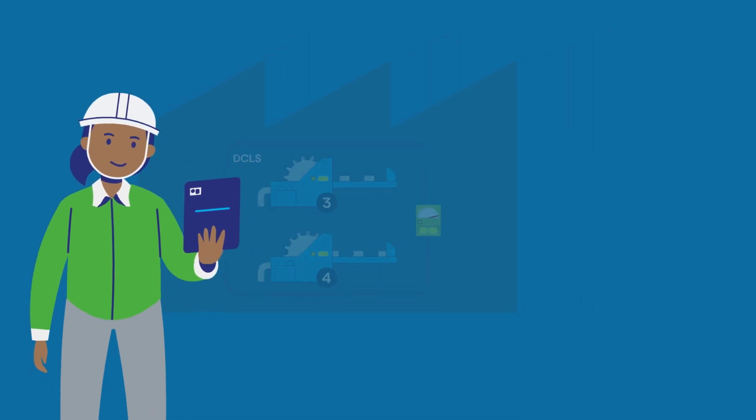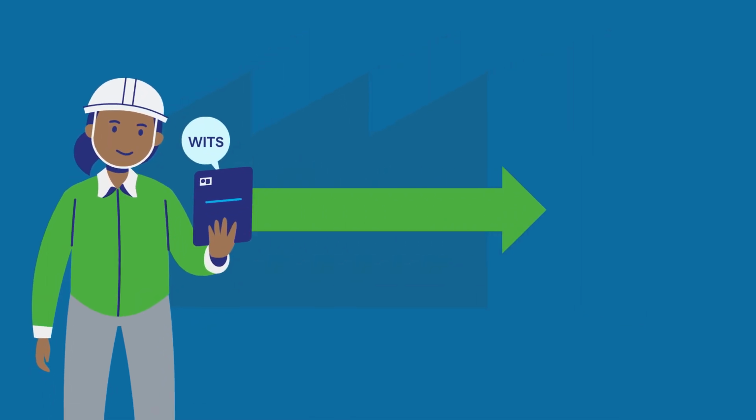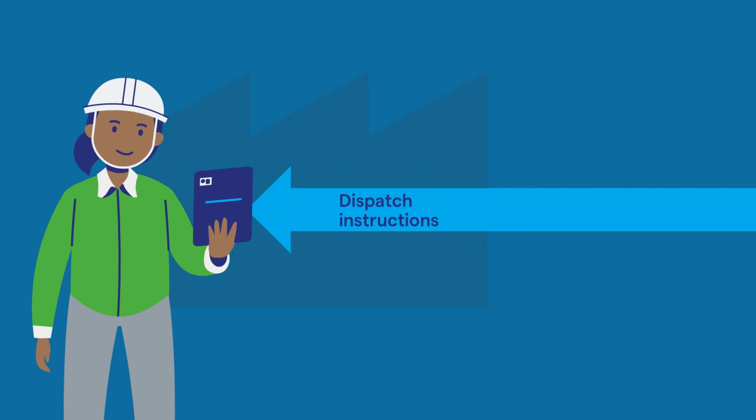Now, as part of the usual running of her factory, Sarah will enter dispatchable bids for each trading period. The bids indicate the megawatt amount of load Sarah needs to run the machines and the maximum price Sarah is willing to pay for that quantity of load. Bids can be entered in up to 10 tranches of load quantity and price. The system operator uses this information as part of its procedure to dispatch the power system.